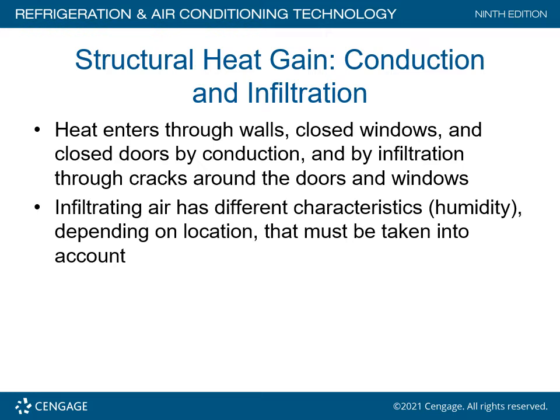Structural heat gain, conduction, and infiltration. Heat enters through the walls, closed windows, and closed doors by conduction, and by infiltration through cracks around doors and windows. Infiltrating air has different characteristics. Humidity, depending on location, must be taken into account.